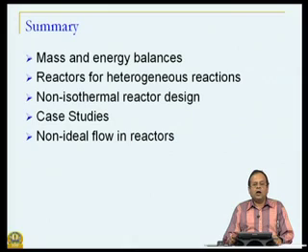For attaining high equilibrium conversions, we need low temperatures, but to attain high reaction rates, we need high temperature. So, an isothermal operation with either high temperature or low temperature will not be good, because we will have to sacrifice on either one of them, either thermodynamics or kinetics.